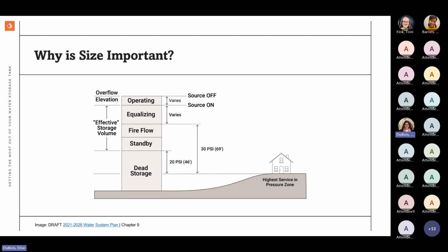When we look at mixers, we also really like to look at what's going on with your water quality. Are we just needing to mix the water? Or do you have THM issues? Do you have other disinfectant byproduct issues? Do you have a biofilm issue? Because sometimes that will relay what else we're looking at.